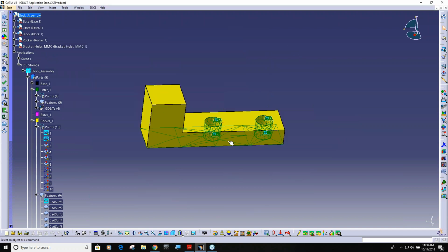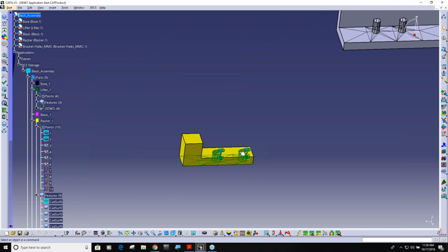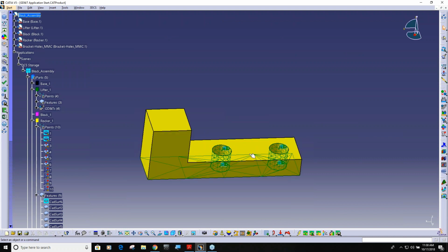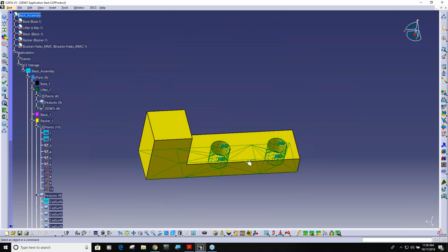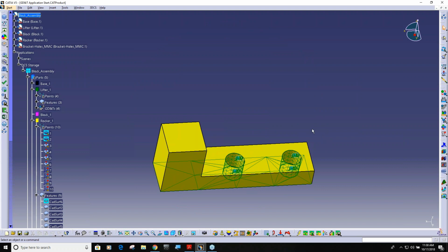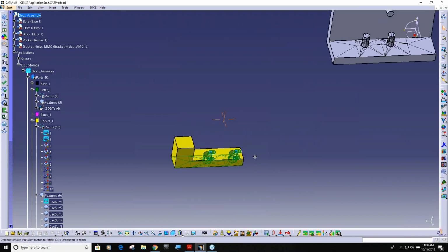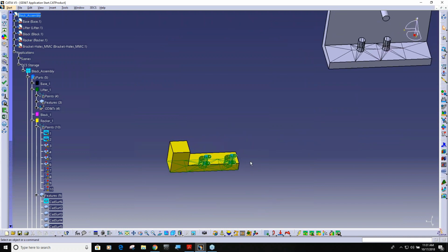Okay, so the issue was, how are the parts constrained when you have a hole pattern as a datum? So we know if I make these two holes datum B, then that's going to control my left and right, my Y variation and my X variation when it's assembled. The constraint system is taken care of by the moves.